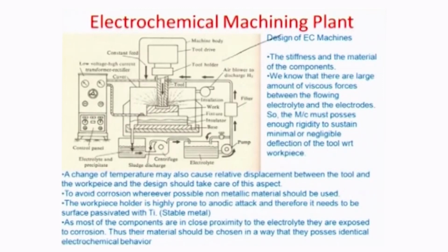So, this is a very nice schematic of what all goes into an ECM system. You should have an electrolyte pumping mechanism. This is the electrolyte storage, and you basically have a pumping mechanism and a discharge mechanism. So, in normal operation you can keep this valve on so that whatever pumps out goes back in, and if it is switched off, then the electrolyte can get circulated into the system. So the electrolyte goes through a filter, this right here is the filter, and it is injected